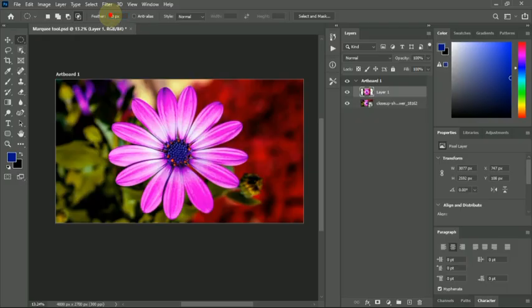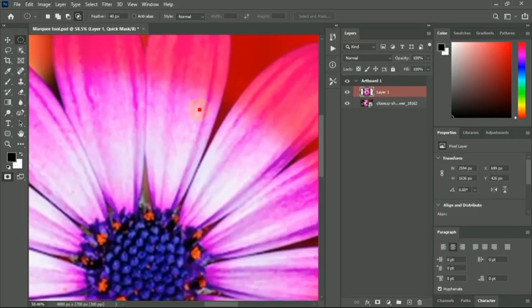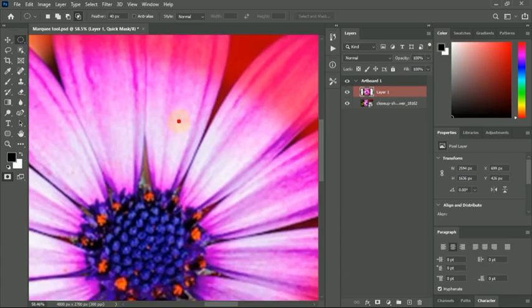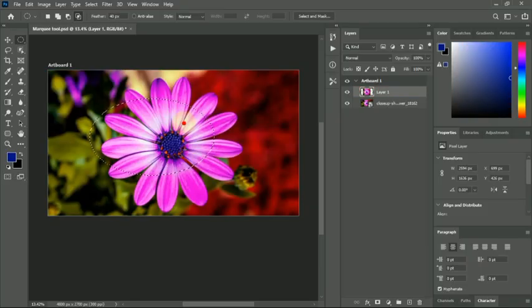Press Q to move out. But when you increase this number, for example, we can choose 40 like that, and now we select an area like that, press Q, you will see that the softness of that selection has been increased. Press Q to move out of the selection.